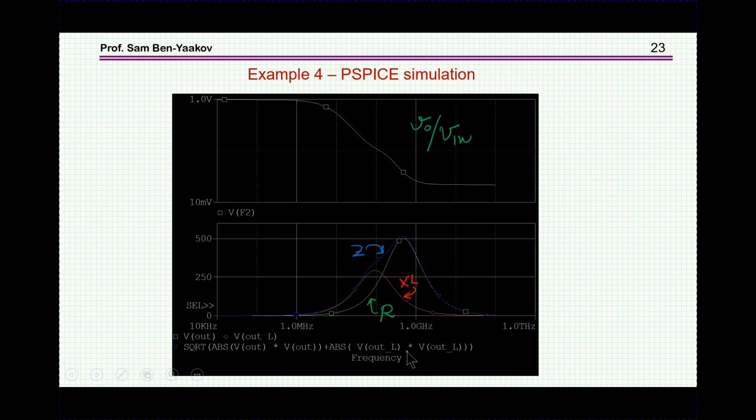So here it is. We see that indeed there is an attenuation due to the impedance developing here. And then, of course, the capacitor is attenuating the signal further, so the Vout to Vin is of this nature. So we see that the bead is actually doing its work and attenuating the high frequency signal.